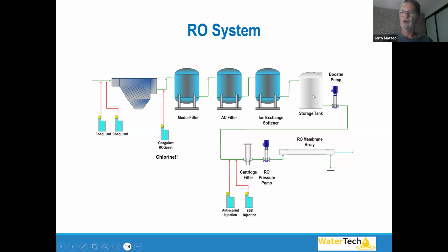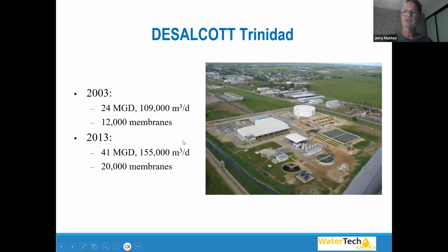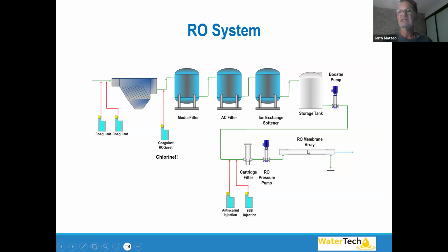Typically you've got a holding tank for, in this case, nice, clean filtered water. And then we would get that water over to our RO with a booster pump. Always, you've got a filter cartridge assembly on your RO. It's kind of your final line of defense for particles. These are more consumable, I call them. Probably most of our customers change their filter cartridges twice a month. And then our high pressure pump, because you're going to see we need pressure to push water through RO membranes.